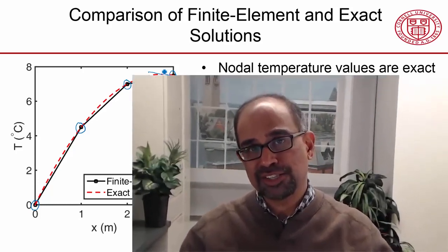And that's usually the case. Whatever you have as a gradient boundary condition like the flux, that's going to be satisfied approximately, i.e. the natural boundary condition is satisfied approximately. The essential boundary condition is satisfied exactly. And when we go to structural mechanics problems, the essential boundary condition is the displacement boundary condition. So if you're fixing a particular edge, that's going to be satisfied exactly. But if you're putting a force, that's a natural boundary condition, and that's going to be satisfied only approximately.